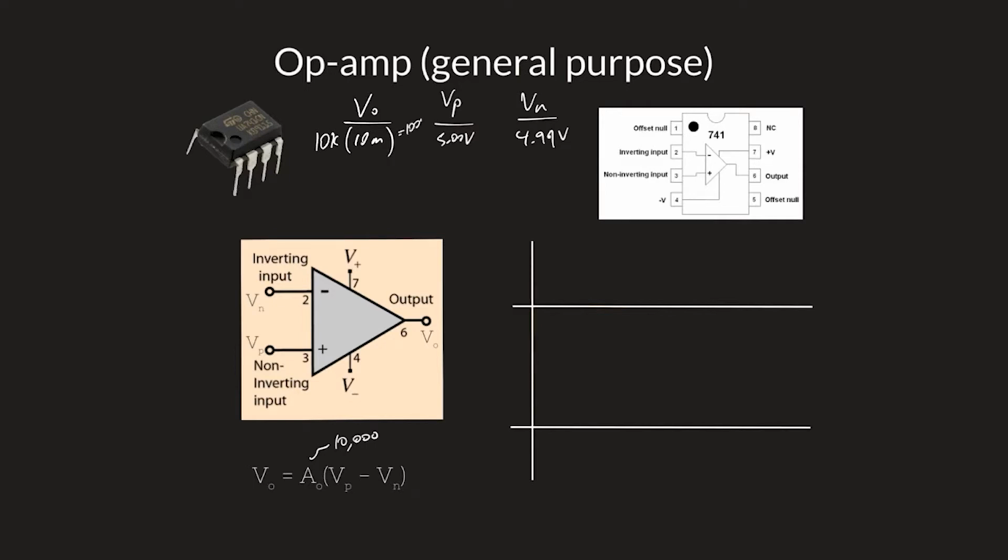So it wants to be 100 volts, but I don't have 100 volts to work with. I have the supply values here, and typical supply voltages are something like plus 15, minus 15, or plus and minus 9, whatever. So this 100 volts is obviously not going to work. If we design it to expect 100, we're only going to get 15.